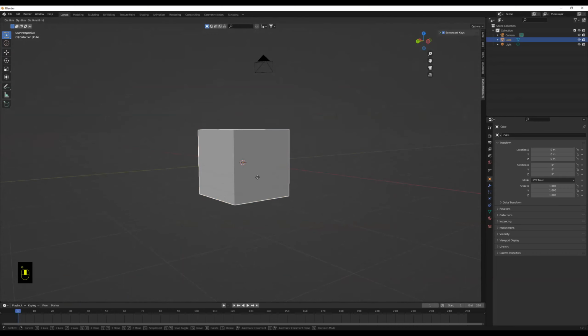Anyways, so we have this gunmetal gray kind of color. We're going to go down there and you see metallic. We're going to crank that to about halfway. So our surface should be kind of shiny, kind of reflective. And then there's also the roughness value, and we're going to bring that down. Not all the way. Please do not go all the way. It'll look kind of weird looking like that. Once you're done with that, we're going to tab.